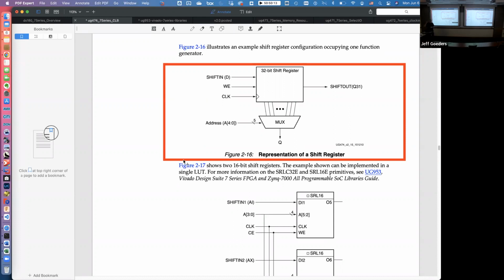Now you're definitely going to want to look at the synthesis report and make sure that if you're expecting 5 shift registers in your design, it says, I inferred 5 shift registers. If it doesn't, you might want to look at your coding style and figure out what you did wrong. Are the tools open enough that you can go in and see the specific one? Yes. And right at the end, we're going to pry open Vivado and start looking around inside.